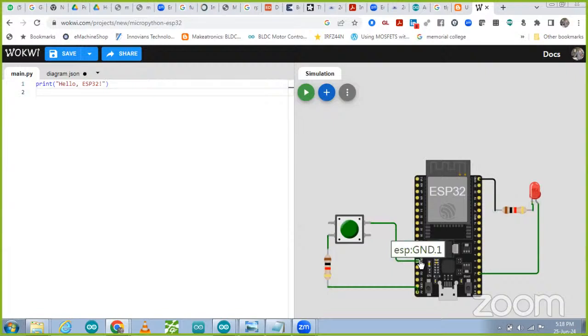Take which pin is ground, ground we are going to connect it. So now we are going to take output from over here. That output we are going to read in a different pin that is given over here. So I'm going to use pin D1, D0, 15, 14, 16 number pin we are using.